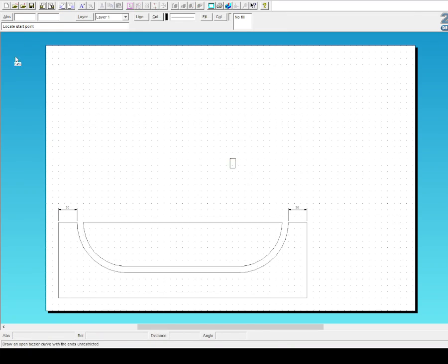Because this is an odd shape and this is an even shape, I'm going to switch on my grid lock, switch off my attach, and draw a couple of points where I want it to be. I'm going to draw symmetrical points here. Now this was again 400, so I'm just going to draw across 200, and draw a line here as well. I'm going to delete away that extra line that I included, because that would be laser cut twice.